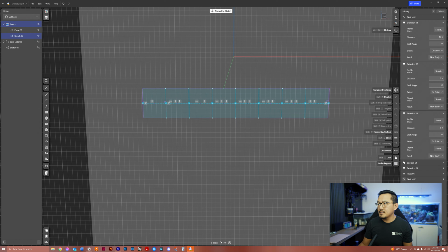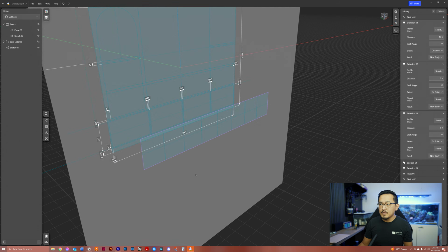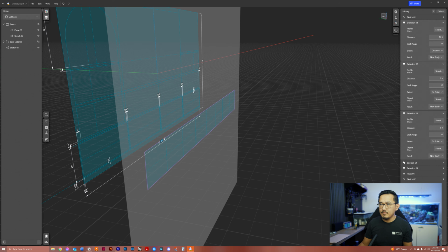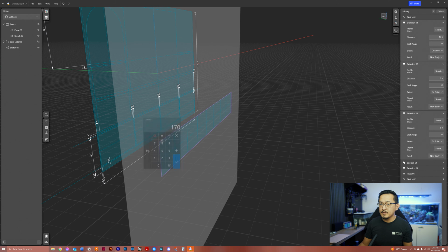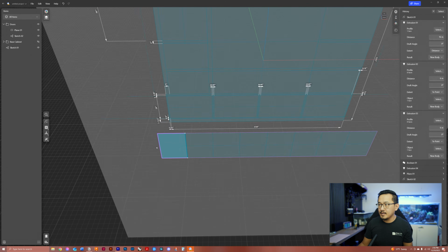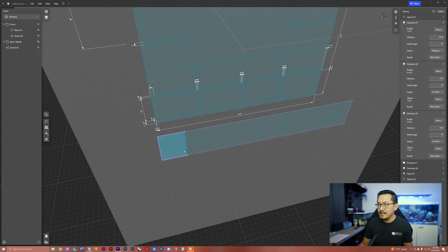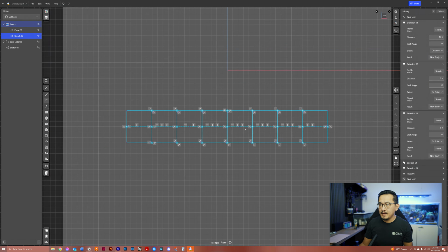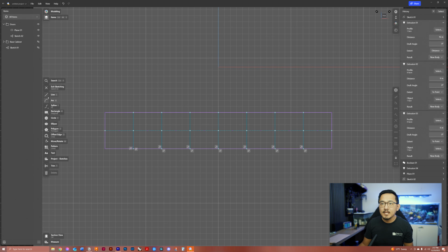Let's go ahead and make these construction lines. So take a look at this, 204. That moves. 170. That moves. 150. That moves. Okay, it looks like everything is working right. Got 2 doors in front of each of our drawers. Counted boxes, so good. All right, so now that I have the lines working, I'm going to establish another line